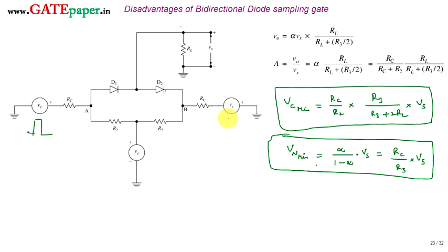if the control voltage is going to be of this nature, then you are going to be getting the opposite in the other half. And the magnitude over here, if it is Vc and Vn, then this must be Vn and Vc. We have taken it in this way. This is minus Vn, Vc and it is Vn, minus Vc. Control voltages are going to be exactly opposite of each other, and that too they are changing at the same instant, but it is not practically true.